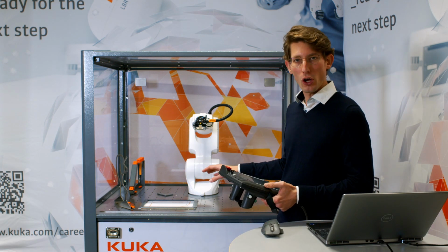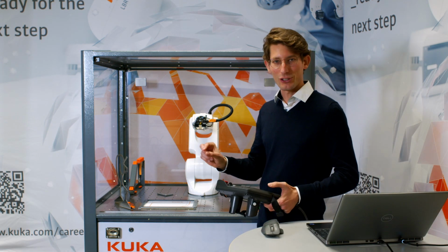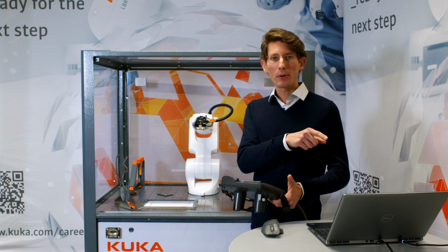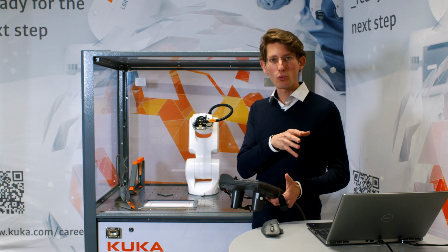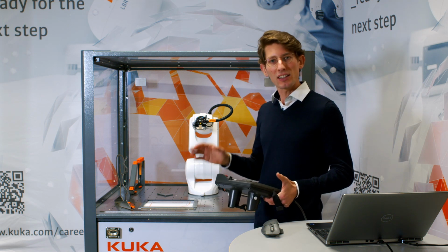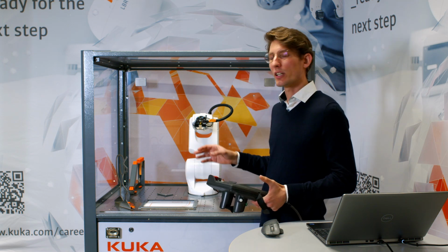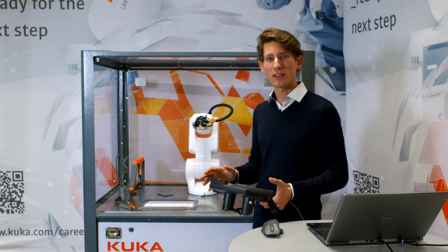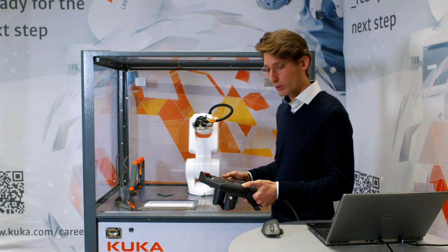Now you just saw that the program is not perfectly on the lines as on the paper. This is just because the paper in the KUKA.Sim simulation world is not positioned the same as in the real world. That's why we can now start to correct the program on the real controller so that it fits perfectly to the real world. Let's get started with that.